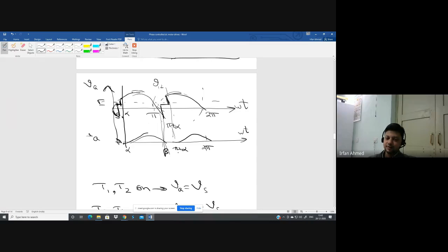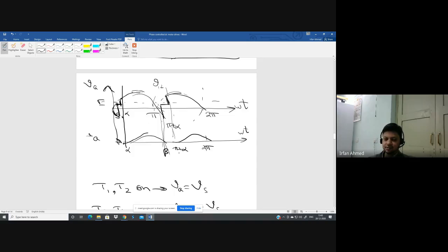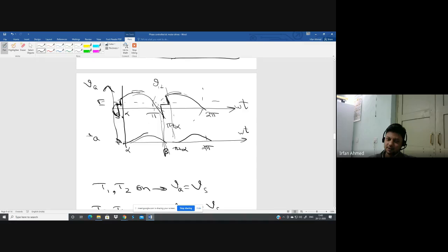The first is, of course, the value of the inductance. Okay? If the inductance is 0, then beta is equal to theta 2. If this E is not present, then beta is equal to pi. Okay? If the back EMF is not present, then beta is equal to pi. Because back EMF is present, beta is equal to theta 2. Beta is not 0.